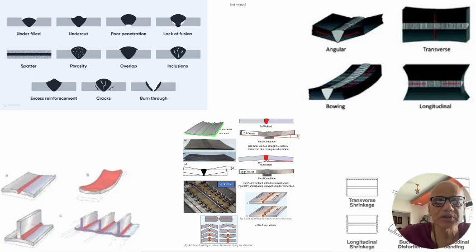And this is what happens if you happen to make a concave weld in a root run. If you give a concave weld, then the thickness at the center of the weld becomes very less. It cannot sustain, and it fails or breaks and looks like a burn through or a crack in the root run or in the penetration. And these are all defects which you can improve only by adjusting your parameters and the angle of the torch or of the electrode.